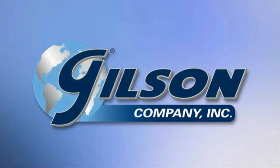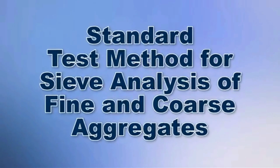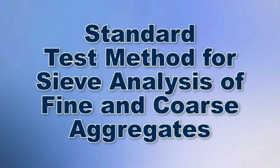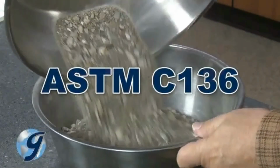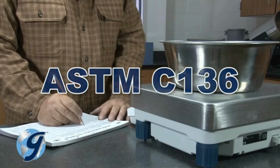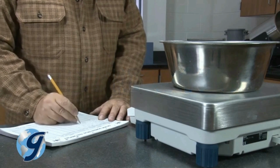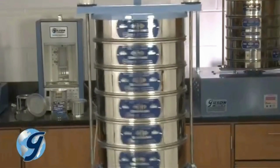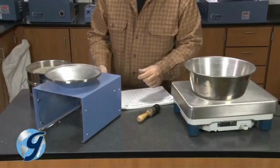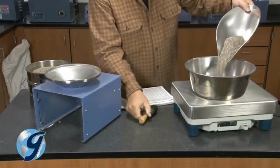Today, we're going to demonstrate the dry sieving test method used to determine the particle size distribution of fine and coarse aggregates in accordance with ASTM C136, where a sample of dry aggregate of a known mass is separated through a series of sieves with progressively smaller openings to determine the particle size distribution of the test sample.